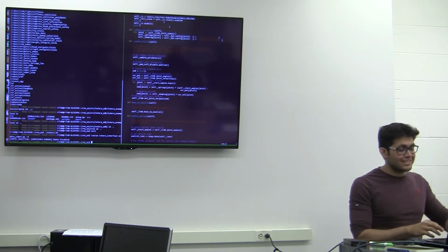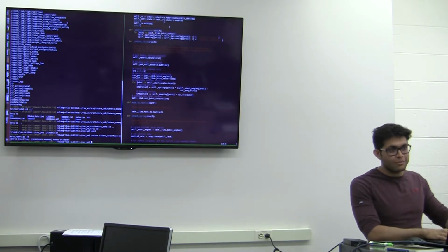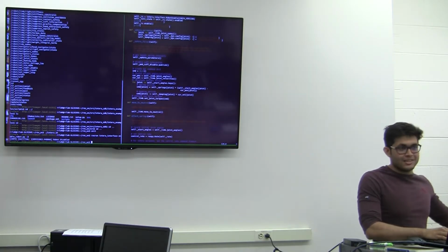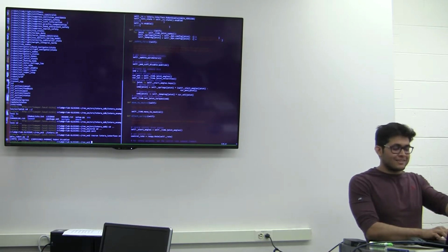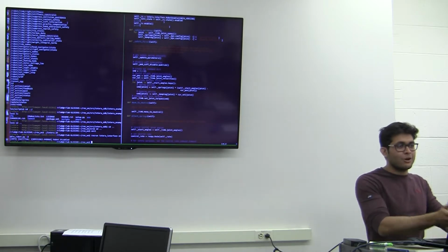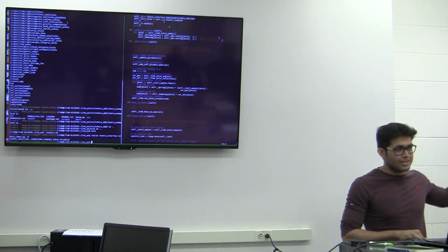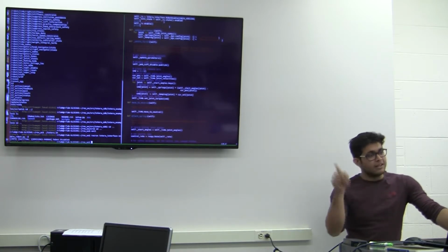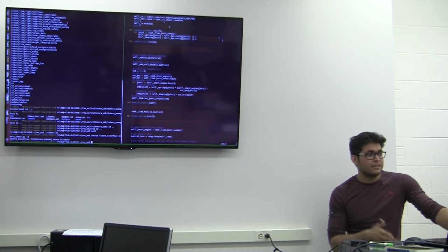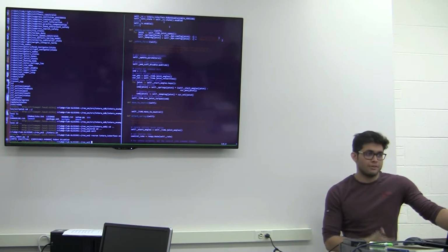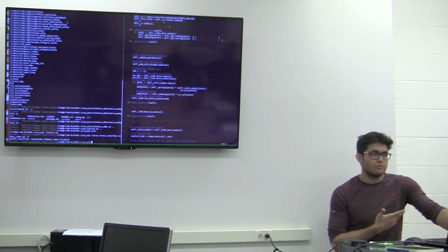So don't panic and just stop trying to work on the computer if the robot is hitting something or has already started pressing. Just use this. If you panic and start hitting Control C, stop, exit, or go outside the script, it doesn't matter, the commands were published before. Some things which are dynamic read it again and again, so they will stop, but some things might not stop. Usually you should not face any issue, but always be careful where you are moving the robot.